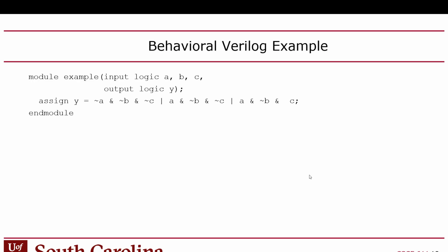And then notice that this is the weirdest thing about Verilog. Well, maybe not, but notice there's a semicolon here. After the module, there's a module line, and then there's a semicolon after it. Why is there a semicolon there? I mean, that module line opens the module, it starts the module. There should not be a semicolon there, but they put a semicolon there. And then they end it with end module, as opposed to like, braces or something. No semicolon after end module. So there's a semicolon on the module line, no semicolon on the end module. Unclear why. And then, of course, in between those is where you have the functional description of the module.